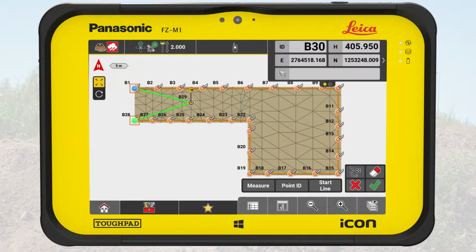As we cannot create the break line in one piece, we must define a new start point. In the toolbar, we tap on the Select Start Point button. We select the next edge point, then the sewage cover point, and the last edge point of this rectangle. We repeat these steps for the second sewage cover.